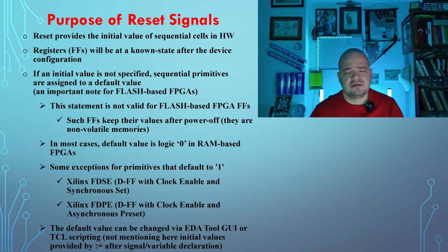But sometimes, for instance, as illustrated before, for the UltraScale+ family, the Xilinx FDSE and FDPE primitives have default values that are not 0 but 1. And this default value can be changed for each register using the EDA tool GUI, graphical user interface, or Tcl scripting.